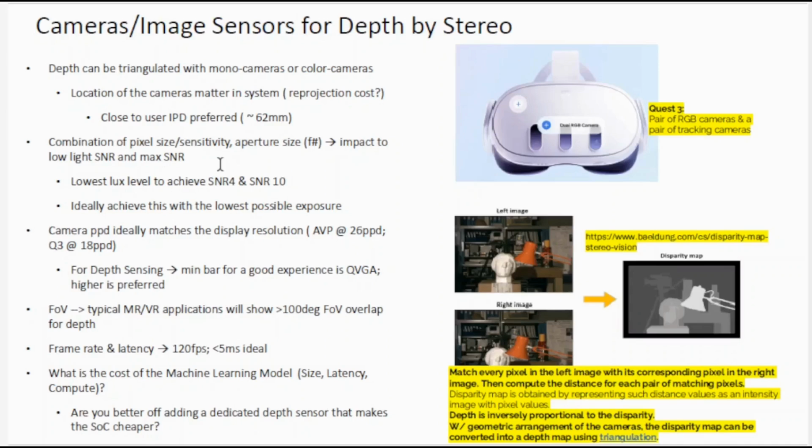If you think in terms of RGB cameras compared to monochrome cameras, you'll generally find that low light performance degrades faster with RGB. Monochrome cameras are a little better. RGB cameras start to degrade faster, so low light's not that good. Those are some of the basic things we look at from the sensor and the camera itself.